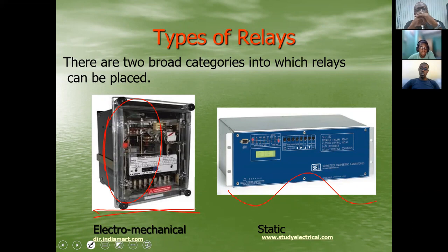Because of the flexibility of the burden impedance that you can connect to the CT, if you replace the high burden of the electromechanical with a static, you would not see much of a problem.